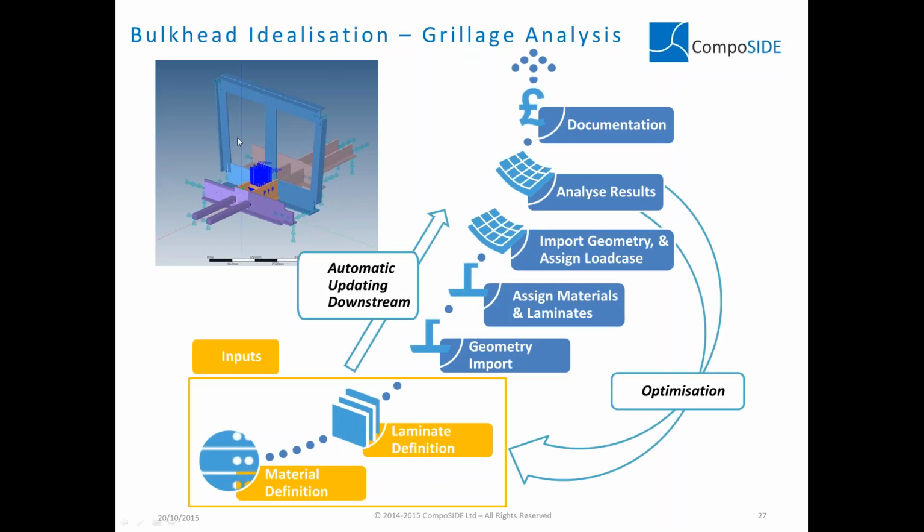Analyze the results, and then I can jump back from FE space into section space, directly taking the internal loads and the reactions to very quickly design those sections to be strong enough and see the load path between them.